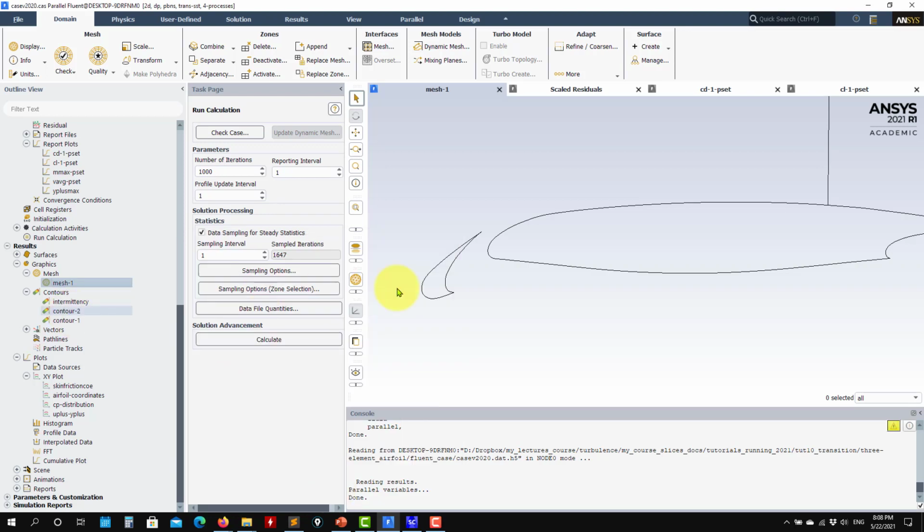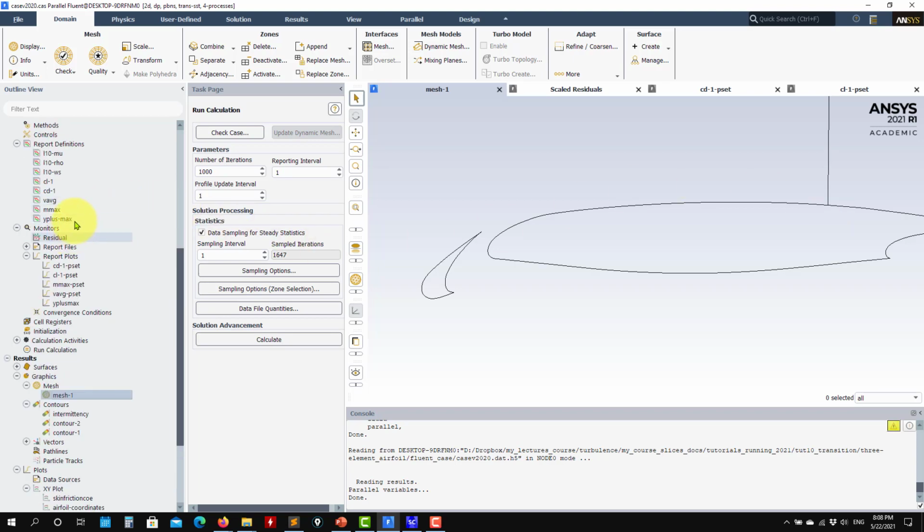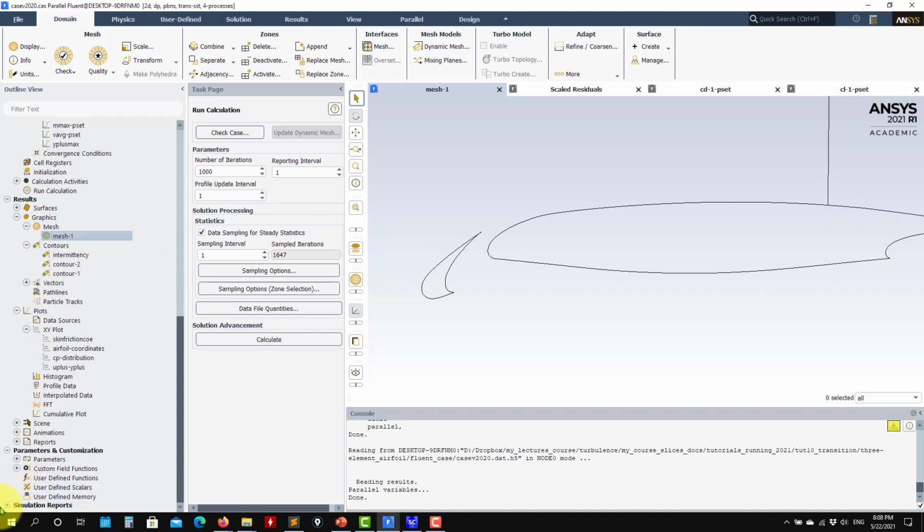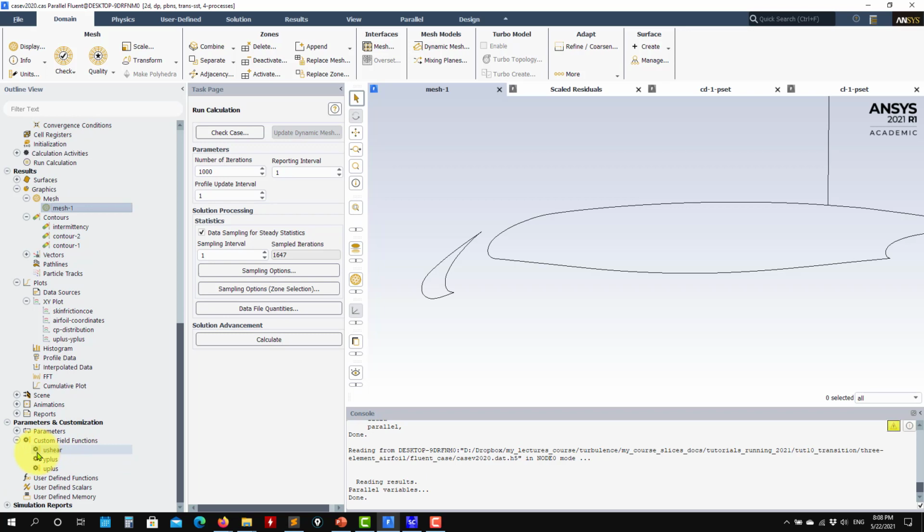Okay, so to do that, remember, line normal to the flow, sample wall shear stress, also sampling density and viscosity. In the previous case they were incompressible, so you know the value. But here I set up the monitors, and I'm setting all these monitors like this. So in this line here, we have mu, rho, wall shear stress, and using that information, you will set your derived quantity, your custom field, so you get the shear velocity, and then compute Y plus, U plus. Okay, so you compute the Y plus in this line, normal to the wall.